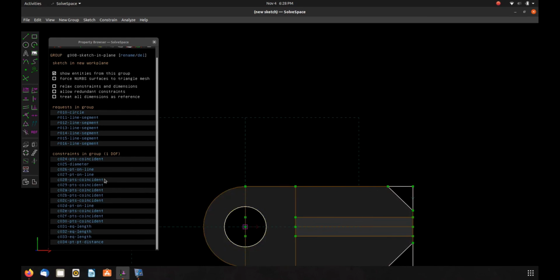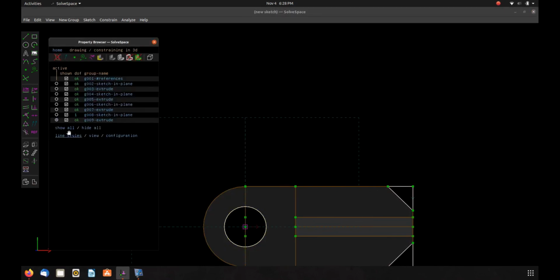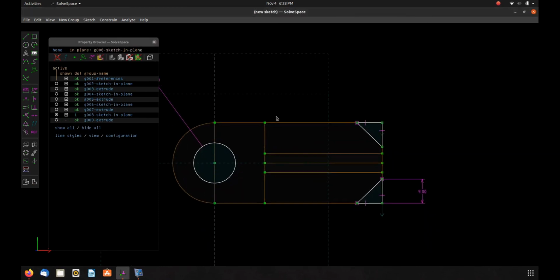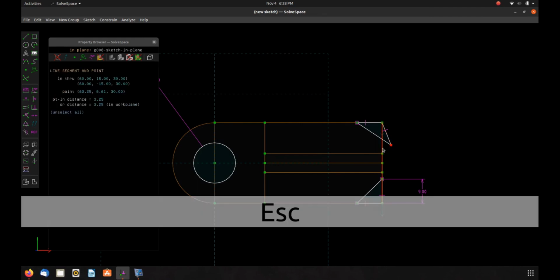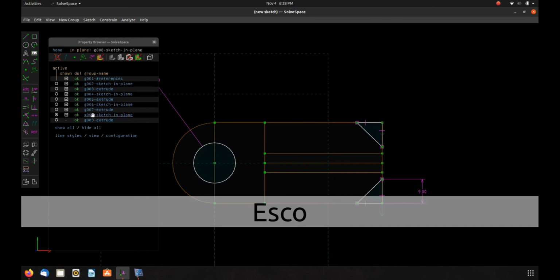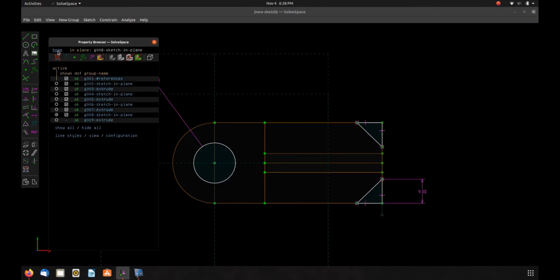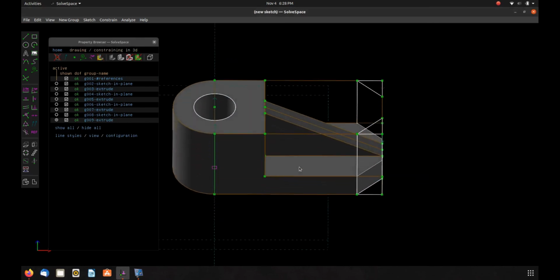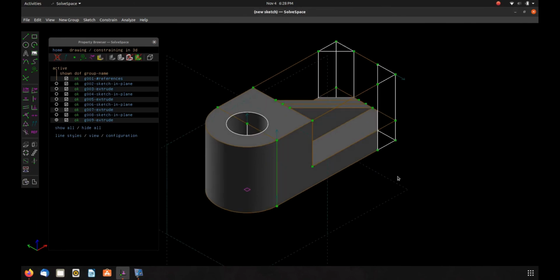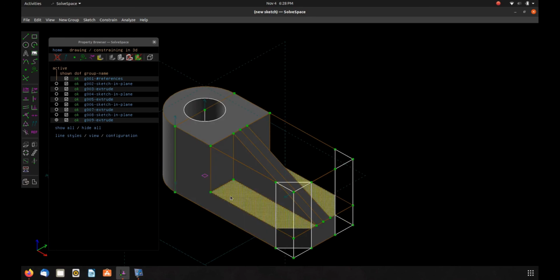So go hit that button to show us the sketch plane. And I pretty quickly realized the issue here. That guy is not fully dimensioned. So I tie that point by pressing O. And now we have 0 degrees of freedom. So we'll roll the sketch or the features forward. Hit isometric view. I don't like that one. That's not what they show. There you go.